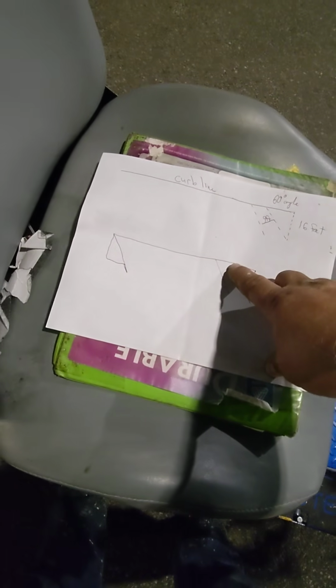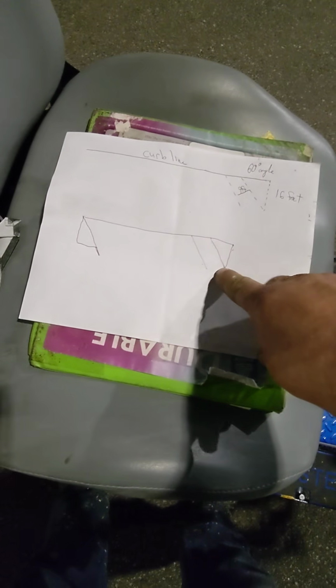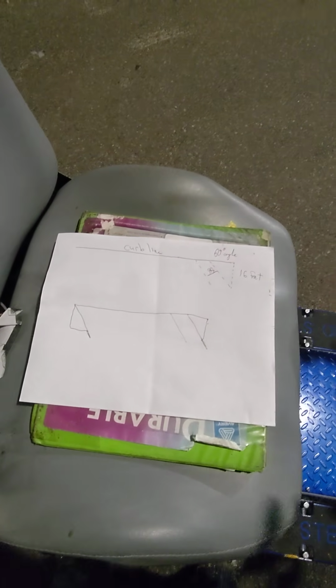If you back up on the curb line pre-marking, you have to back up on your outside mark pre-marking. So you don't want to back up on this one and go forward on this one. You want them all measured the same exact way. There could be a slight variance between going forward or reverse. So always pre-mark in the same direction. But then once you got 2 marks down, then you can go forward the rest of it.